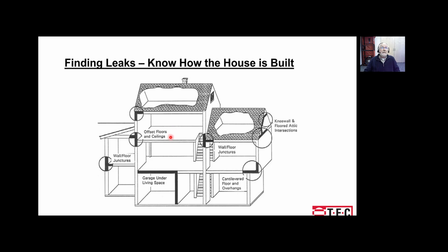So for example, next I'm going to talk a little bit about how using a blower door with an infrared camera together is important. So imagine in this house we set up a blower door and we depressurize the house, and there happens to be a connection here where the attic above the porch or sun space is connected to this exterior wall, and what happens is air comes in from the attic into this wall, and it might find a connection into the ceiling cavity between the first and second floor of the house.